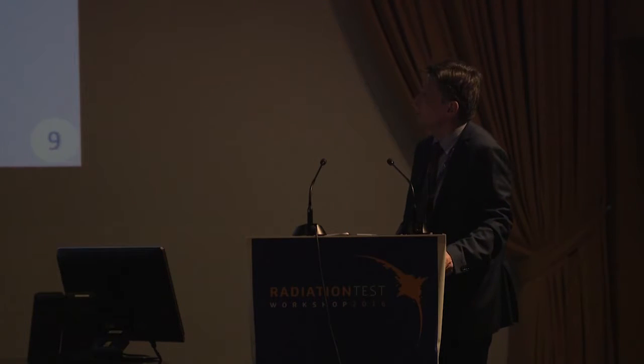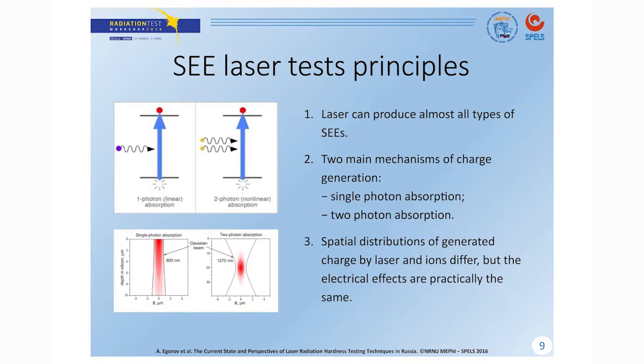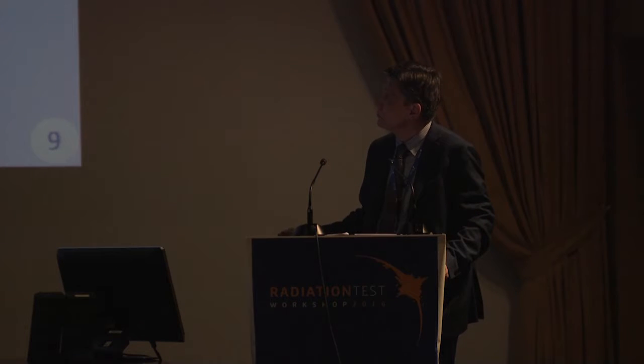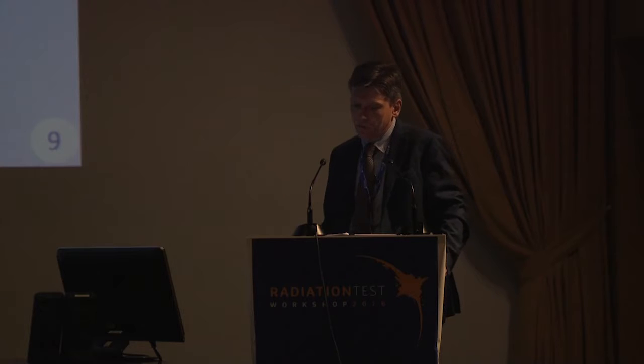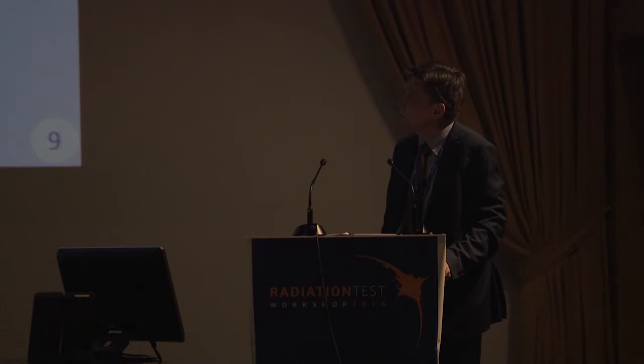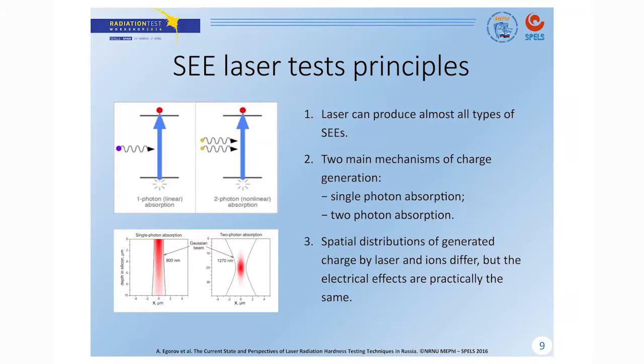Here are some basics of laser simulation. Laser can be used to test all types of ICs and can simulate almost all SEE effects in them. So we can use single photon absorption, when photons have enough energy to make electron hole pairs, and also it is possible to use two photon absorption.